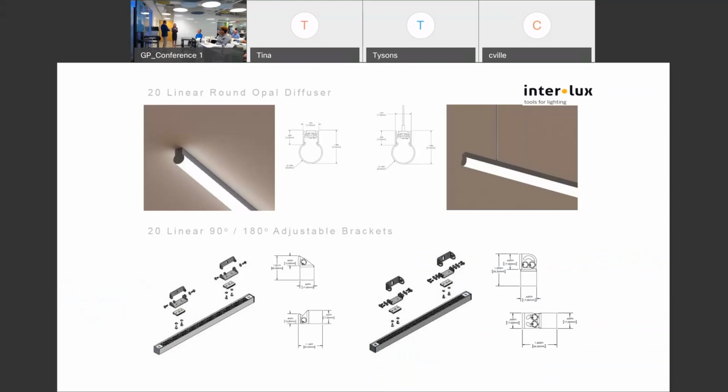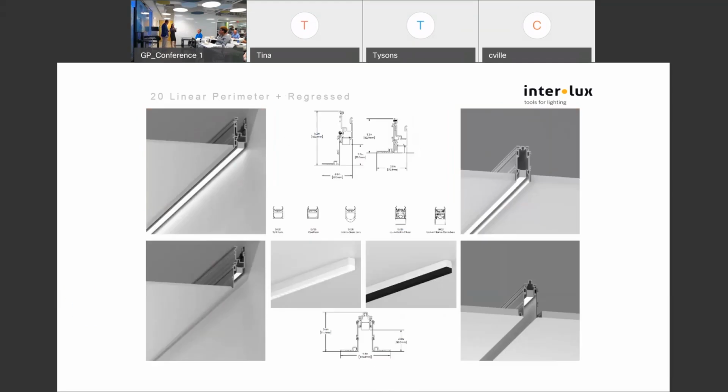So most of the challenges we have here in BC is, here we are 4 years later, a driver went out. So it's just that the drivers then get replaced. But they've also gone from a whole linear LED strip to little segmented pieces, and these are clipped in. So let's say just these diodes went out, you don't have to replace the entire linear run. You can actually just replace this small section. So it's sustainable now. We weren't like that when we first invented it.